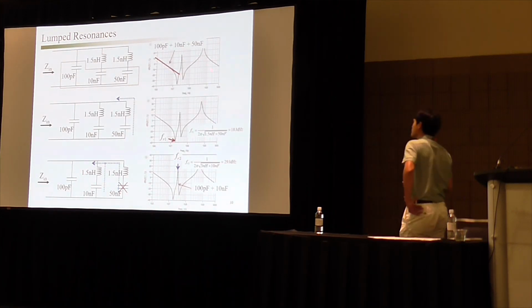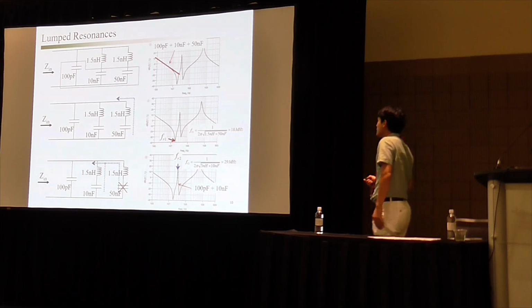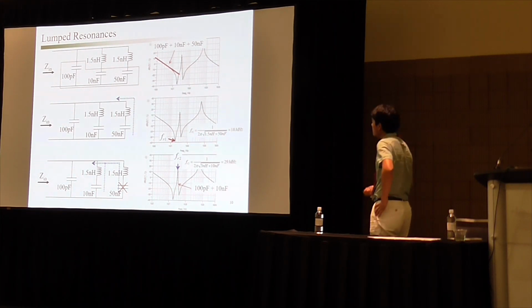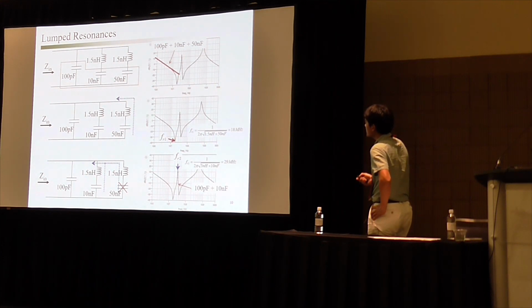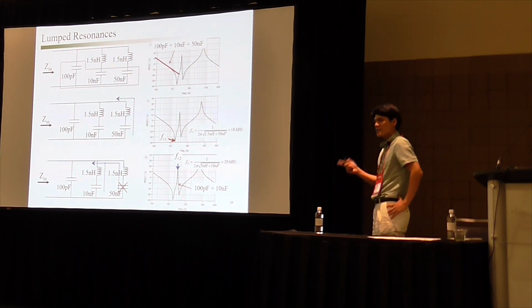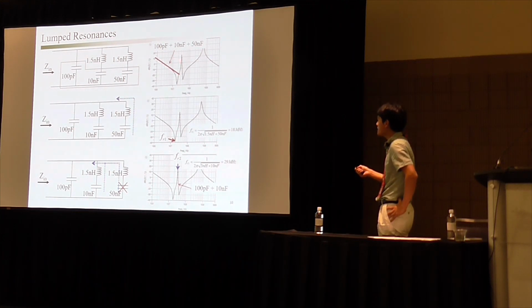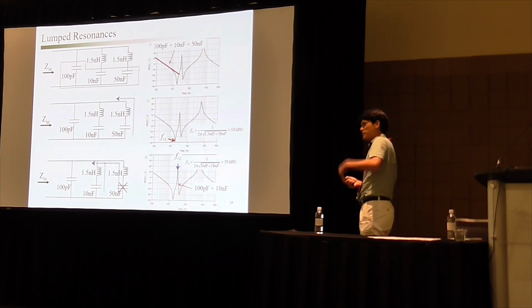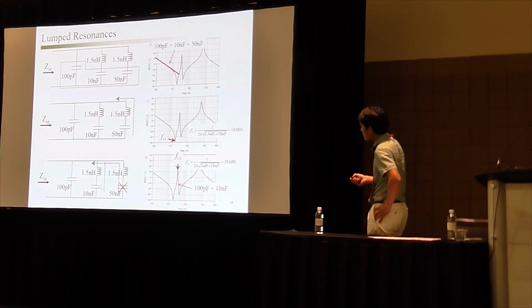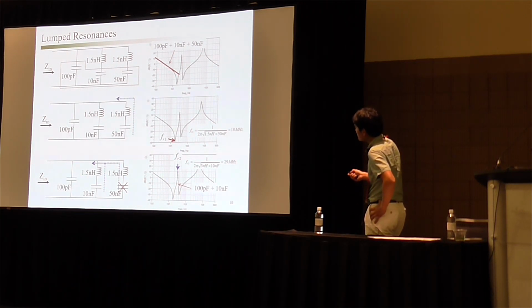So here is the impedance profile seen by this IC. This is a very typical impedance curve you may see on your PCB design. First, higher impedance means that if you have some current at this frequency, the voltage is simply impedance times current, right? So with higher impedance, there's a high risk that you have large voltage fluctuations. So of course, in this impedance curve, lower impedance is better. Let's first start off with the low frequency.